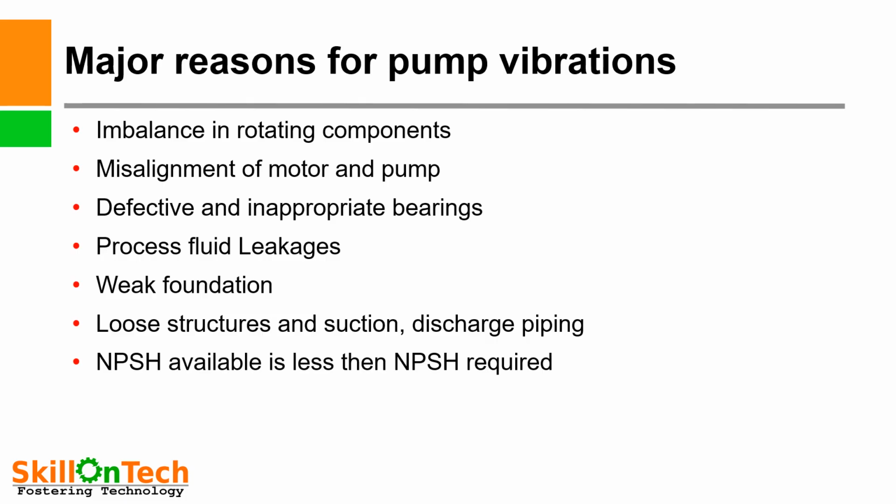Major reasons for pump vibrations: imbalance in rotating components, misalignment of motor and pump, defective and inappropriate bearings, process fluid leakages, weak foundations, loose structures and suction discharge piping, NPSH available is less than NPSH required.